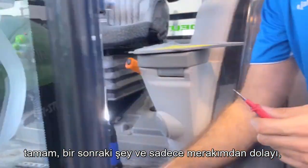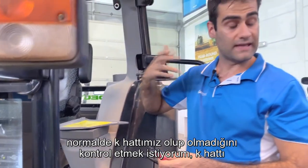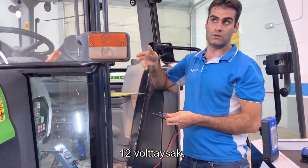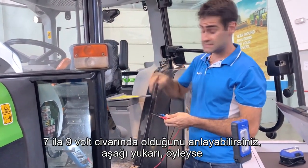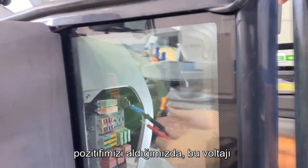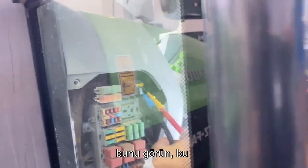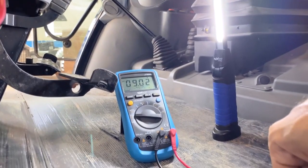Okay, the next thing, and just for my curiosity, I would like to check if we've got some K line. Normally, the K line has around 70% of the battery voltage. If we are in 12 volts, you can figure out that it's somewhere around 7 to 9 volts, more or less. So let's check if taking the ground and taking our positive, we see this voltage in one of the pins. See this one? This is in pin number 1, and we've got 9 volts.